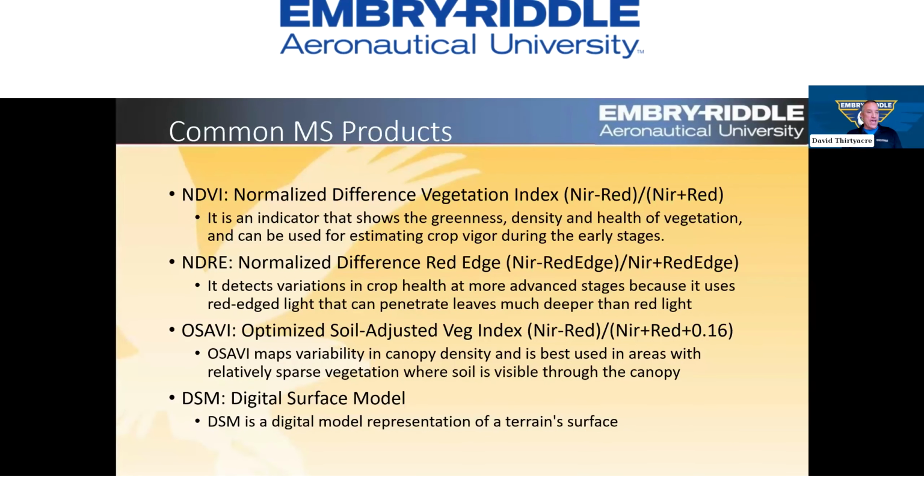That's pretty neat. And then again, I'm going back to this one about irrigation and erosion, which is huge in a lot of places. Just creating that digital surface model to understand how the water is going to flow and where it's going to go is going to be a really big deal. So never forget that the DSM is the place I always start with and go from there, because that can tell you an awful lot about what's going on.